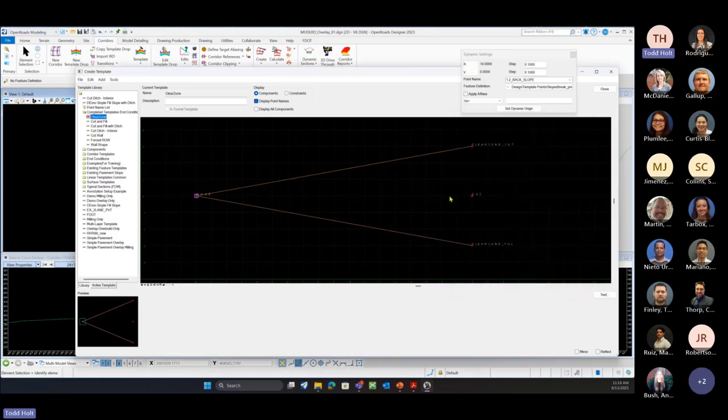And what that is doing is we have a known distance from our hinge point of, say, 18 feet, and we want a variable slope that's going to go 3 feet above or 3 feet below that. So we have a variable slope. So it's going to come out, find the terrain at 18 feet out, and then we can tie it in above or below 3 feet.